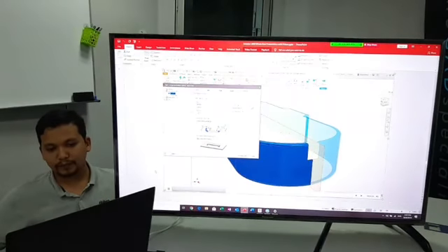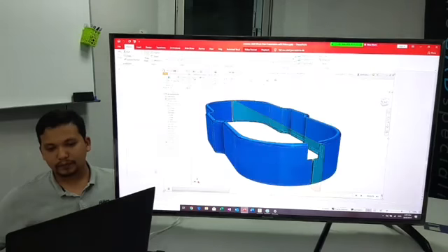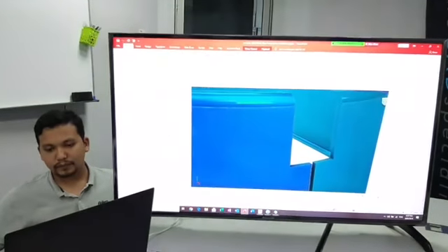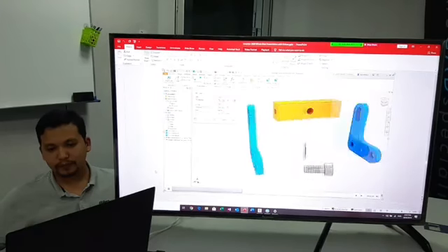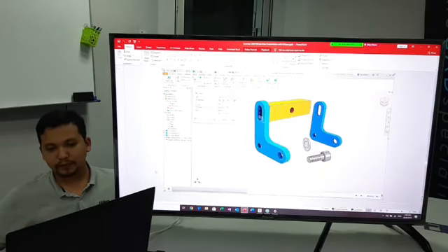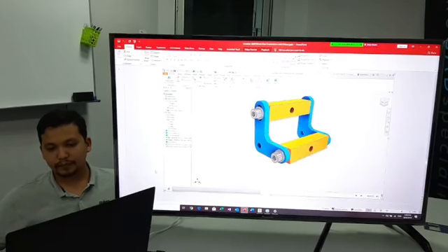Mirrored sheet metal components now automatically link to the source file, ensuring parts are properly associated. When creating joints between components, you can now select the center of both curved and straight slots. This eliminates the need for multiple constraints when working with slotted features.